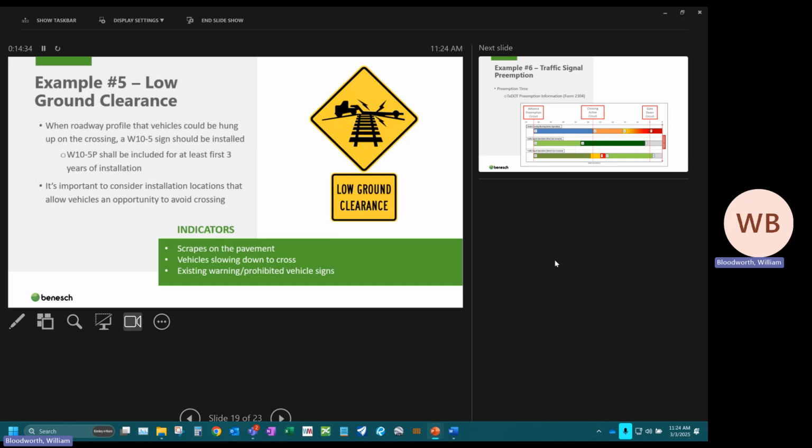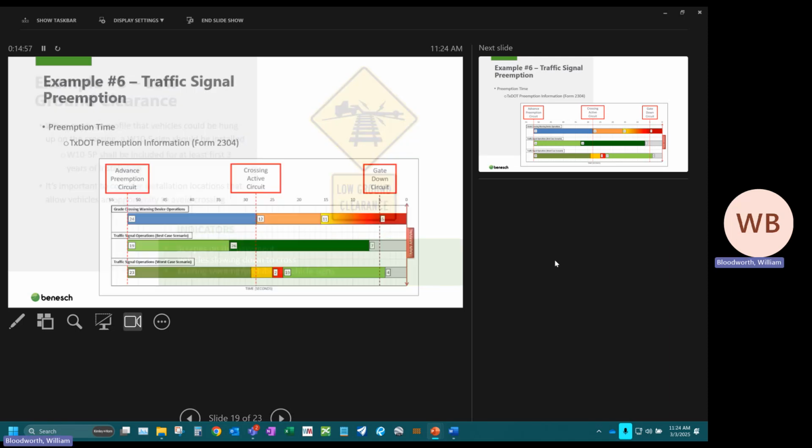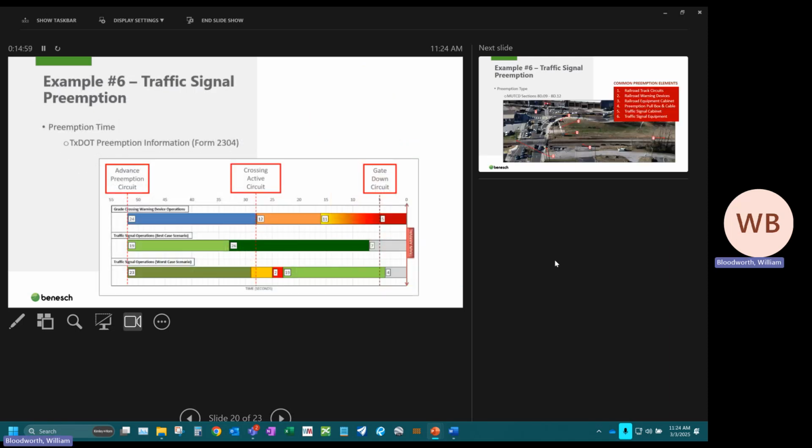And then the other way I want to talk about is if you are designing a new profile over a railroad crossing, that guidance is in AASHTO 9.12.2. So just a couple sections before the sight distance. And really it has great diagrams and how you should do it, but the general guidance is 30 feet from the outside rail. You don't want more than 3 inches of change of grade so that we're not creating these hazardous situations.